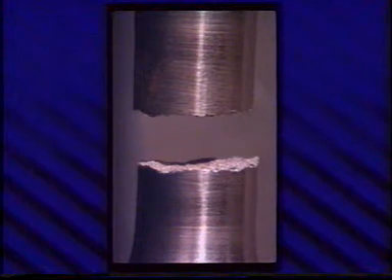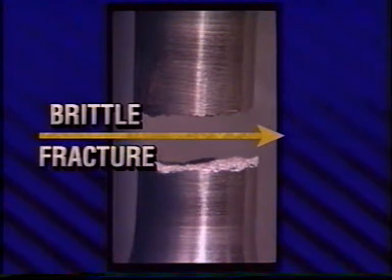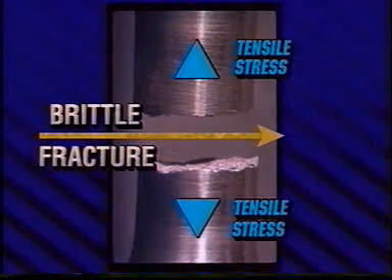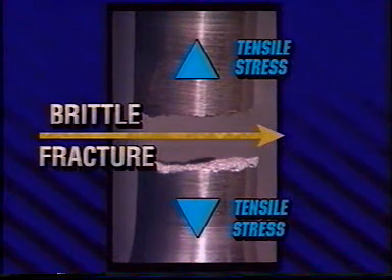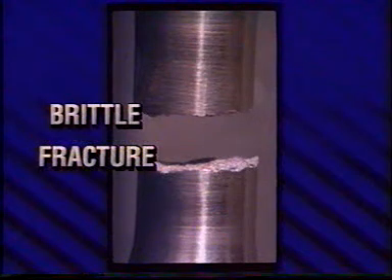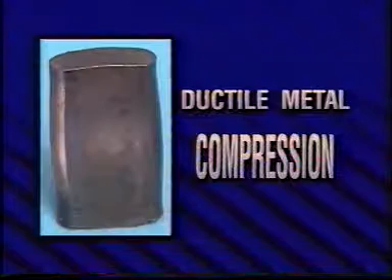In brittle metals stressed in pure tension, the fracture is essentially perpendicular to the tensile stress, straight across the section. There is little or no plastic deformation before fracture occurs. Truly brittle materials cannot deform plastically, as ductile or moderately ductile materials can. The characteristic appearance of fresh fractures in brittle metals is usually bright and sparkling.